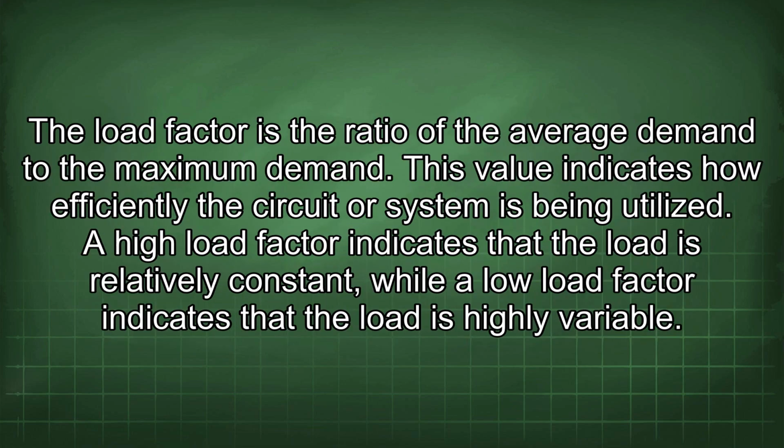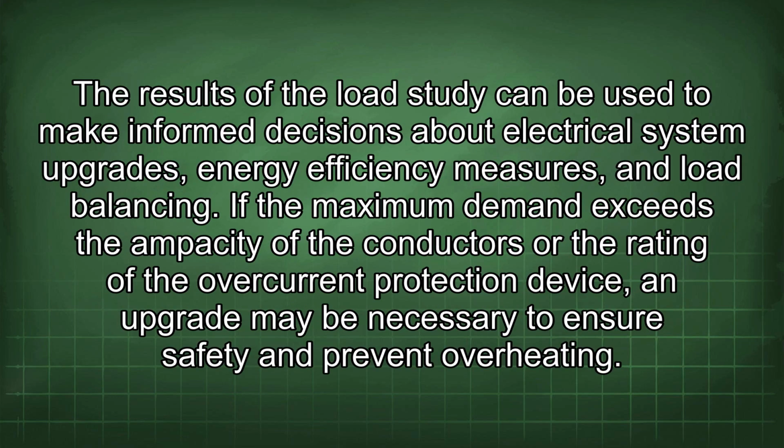The load factor is the ratio of the average demand to the maximum demand. This value indicates how efficiently the circuit or system is being utilized. A high load factor indicates that the load is relatively constant, while a low load factor indicates that the load is highly variable. The results of the load study can be used to make informed decisions about electrical system upgrades, energy efficiency measures, and load balancing.